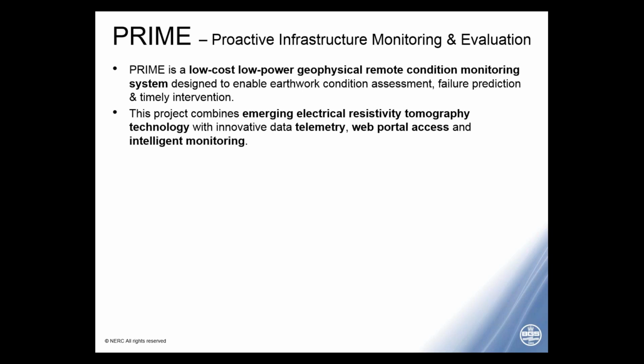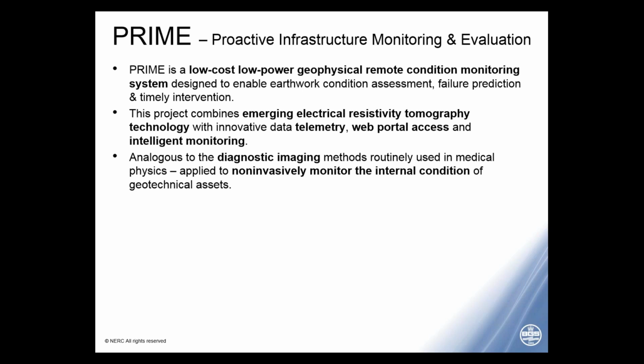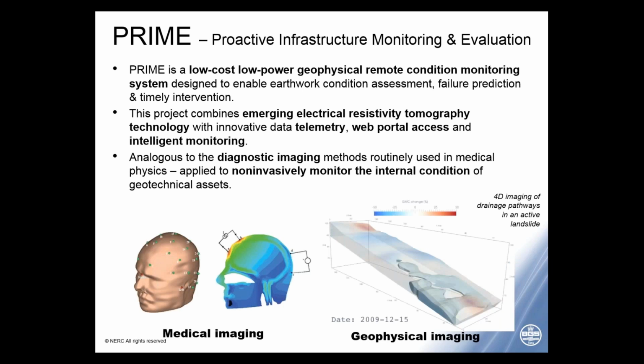So the technology combines a technique called electrical resistivity tomography, quite a well-established geophysical survey technique, with telemetry and web portal access for intelligent monitoring. And really the concept here is that we're applying diagnostic imaging methods, very similar to those used in medicine, for example, to non-invasively monitor the internal condition of geotechnical assets.